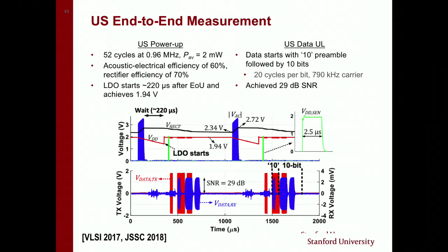And if you look at the waveforms, these are our measured waveforms we presented at VLSI last year. There are different sequences on how you power up and communicate. The mindset here was you want to avoid ultrasonic waves when you're measuring pressure. Because one of the things, again, we learned the hard way, is that as you have ultrasonic waves in tissue and you try to measure small variations in pressure, they will interfere. So the way we operate this is a full TDD system.